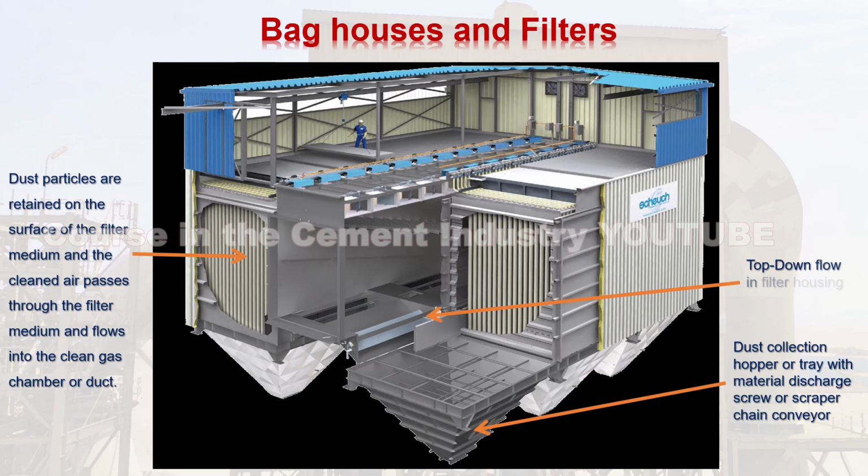Top-down flow in filter housing. Insulation to avoid undershooting of dew point, hot gas version. Dew point can be defined as the minimum flue gas temperature below which the moisture settles on the bags, and particle adhesion takes place.